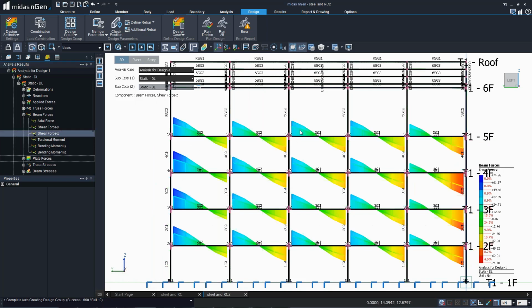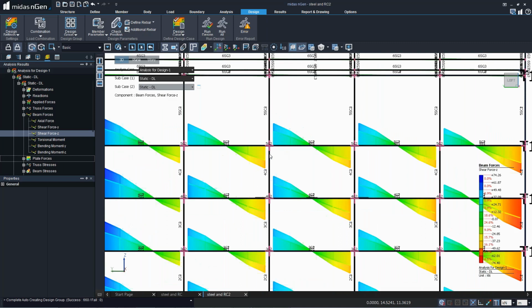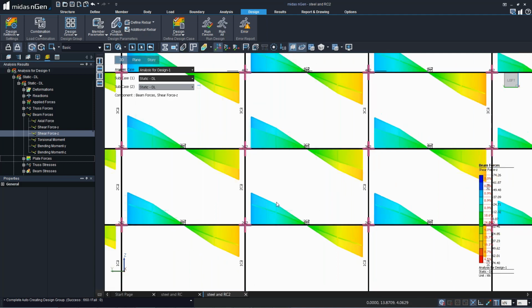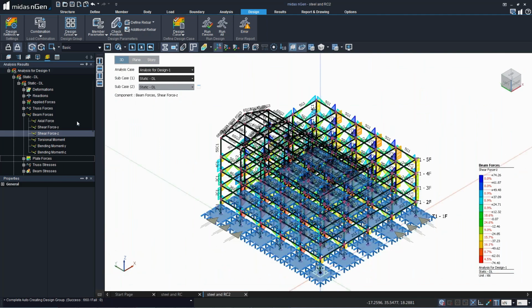So this is the shear force, and as we had used a rigid zone, we can see that the location wherein our beams and columns are intersecting is not considered for the design purpose. So that's how we can optimize our design results. Basically, when we are finding the moments considering the center to center modeling, then we are getting higher moments at the junction locations. So to avoid that, we can use the rigid zone. Okay, so that's one part.